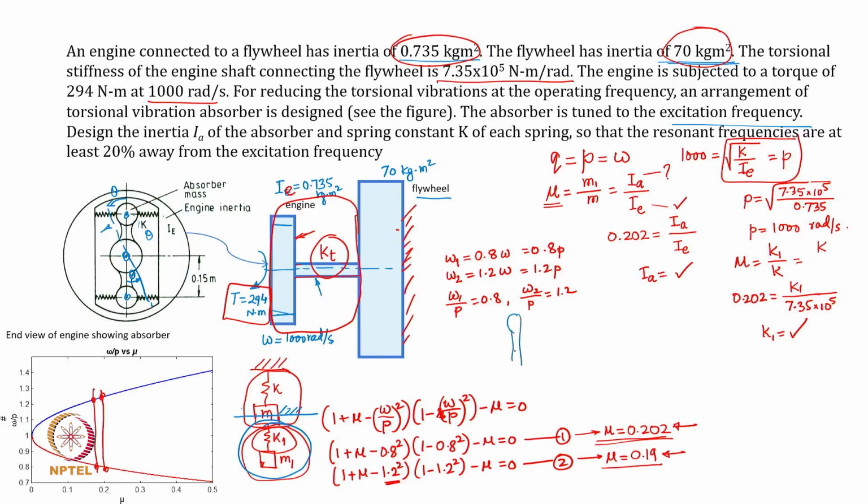Now I will use a little simpler shape of this, hinged here, and then there is a spring here, there is a spring here, and all the spring constants are assumed the same, identical springs. What will happen if I assume clockwise theta and theta double dot? Can I write the governing equation of this torsional vibratory system?